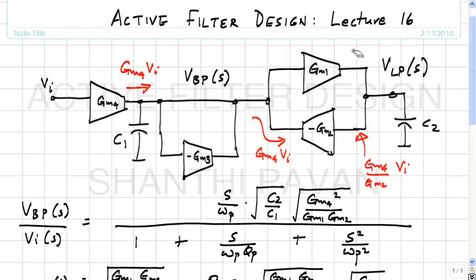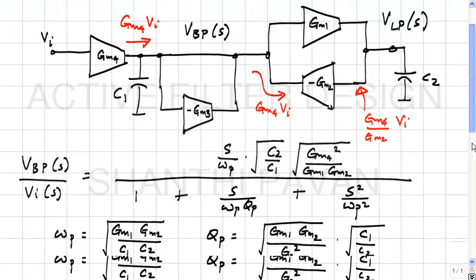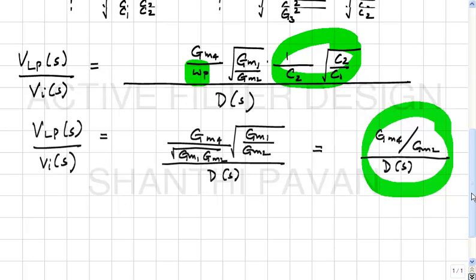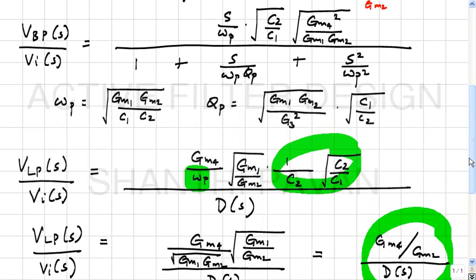Okay. So we therefore see that the band pass node and the low pass node respectively give the band pass numerator and the low pass numerator, and by fooling around with these ratios GM1, GM2, GM3 and GM4 and all this other stuff, you will be able to get a numerator in the low pass which has an arbitrary gain.